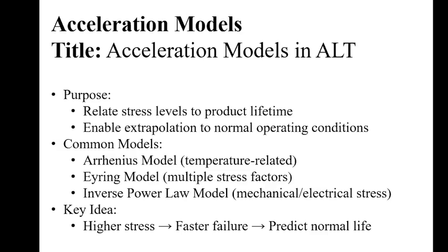Common models include the Arrhenius model, which is used for temperature-related stress, the Eyring model, which can account for multiple stress factors simultaneously, and the inverse power law model, which is often applied to mechanical and electrical stress conditions. The key idea behind all these models is that increasing stress leads to faster failures, enabling quicker data collection and more efficient reliability predictions.